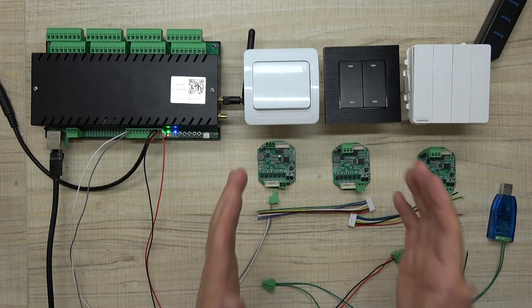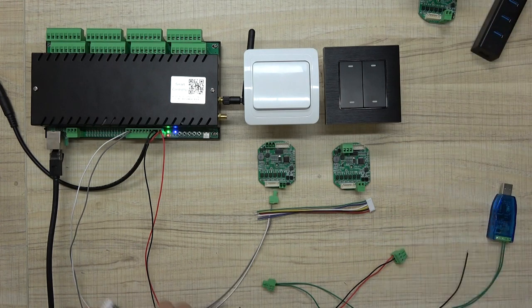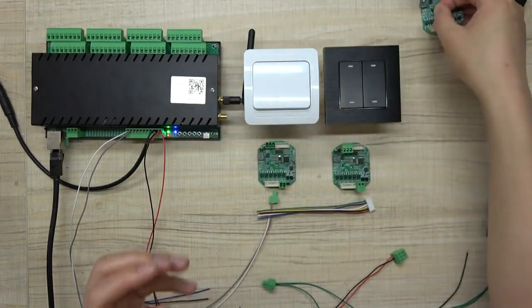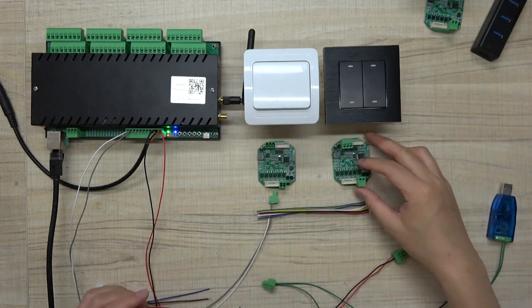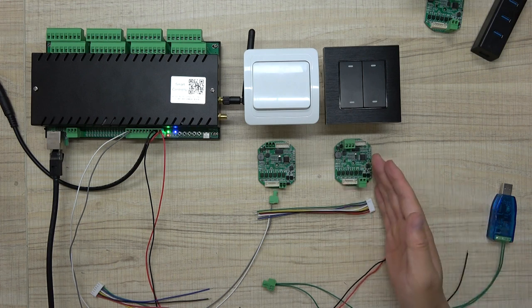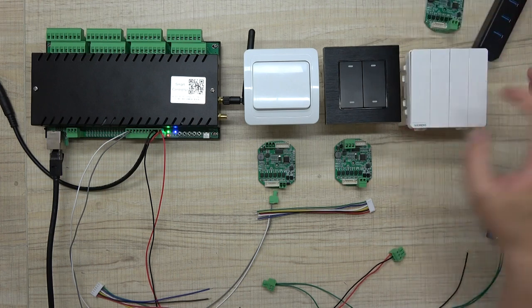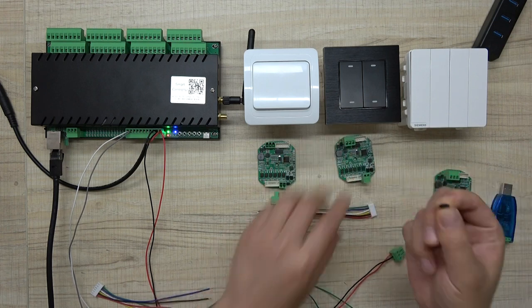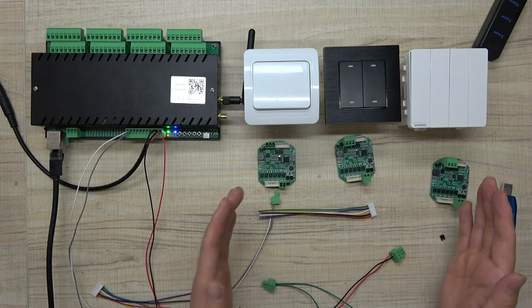If you have only 2 switches, just remove this one and not this one. Only these 2 switches. So you should remove this jumper and connect it to these pins on this board here. So the resistance of the RS485 must be enabled at the last terminal. Maybe if you have 3, maybe if you have 4, always use the last one. The jumper is always on the last one. So that will let the RS485 bus work stable.